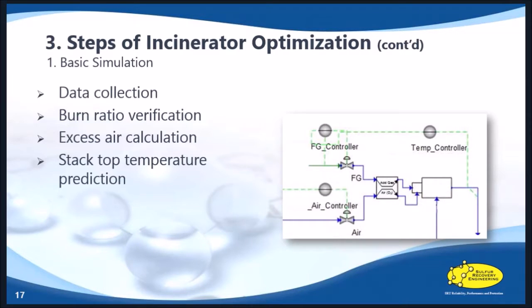Basic simulation. Before we apply for a waiver or start the field testing, SRE collects data such as the present operating condition of the sulfur recovery unit and the feed stream compositions to the unit, such as acid gas, fuel gas, sour water stripper gas, or any other feed streams going there. We also collect detailed design drawings on the stack and incinerator as well.